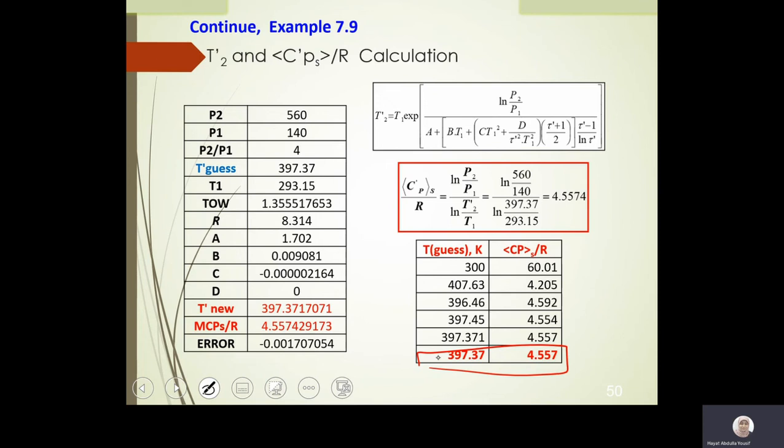Of course, the beta value and Cp value are supposed to be given in the question in case you want to use those equations, because equations 7.25 and 7.26 are based on constant Cp, and the beta value is supposed to be given for the pump. I gave you the beta value and the Cp value, so in this case it's just direct substitution. For W isentropic, we multiply the specific volume by delta P. I found the specific volume from the thermodynamic table, table F1, because it was saturated liquid at the given pressure and temperature. The pressure difference is given in the question.